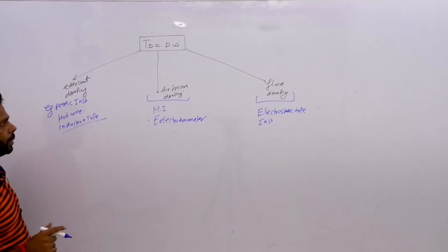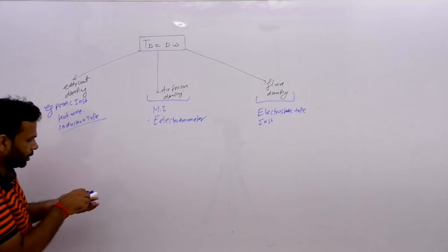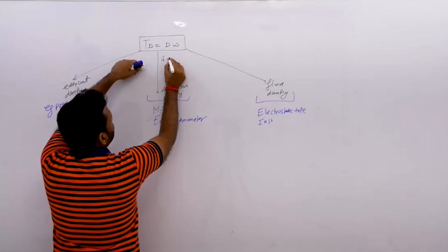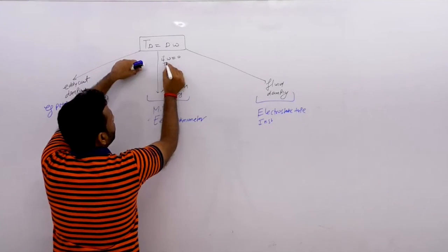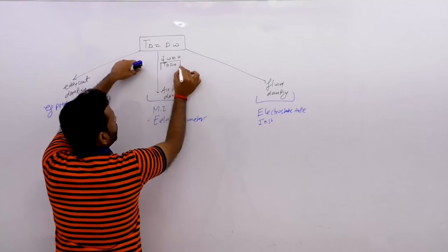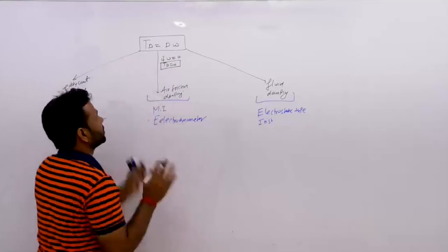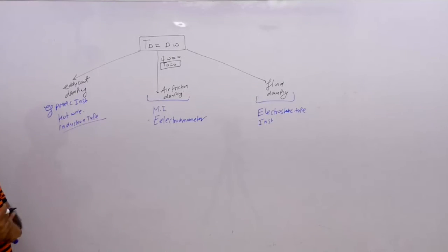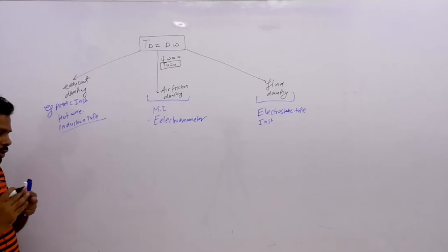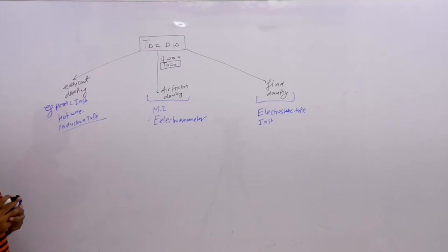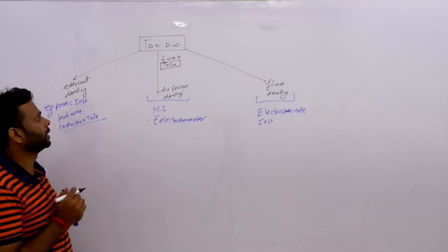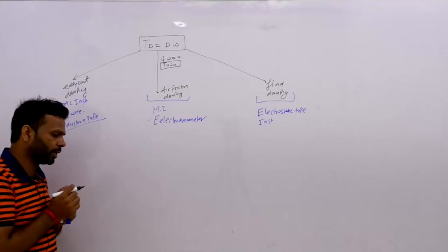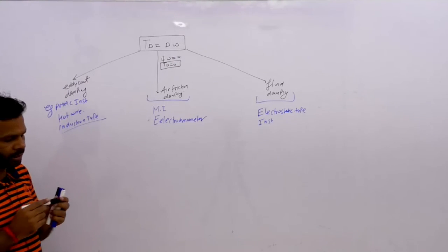Now if you see from the damping torque equation, if speed is zero, then your damping torque is zero. That means the damping torque exists only when there is a movement or motion. If there is no motion, then we only have two torques, the deflecting torque and the controlling torque. Now let's see how the damping is provided in the case of your PMMC instrument.